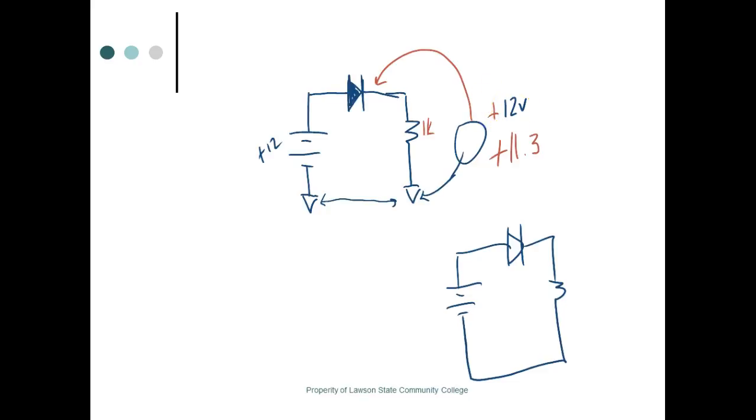Well, Rich, you said the cathode had to be negative. No, Rich never said the cathode had to be negative. We said it had to be 0.7 of a volt less positive. So that means if I put my common right here and measure there, it would measure minus 0.7. But normally we don't make measurements across. We try to make it relative to common.